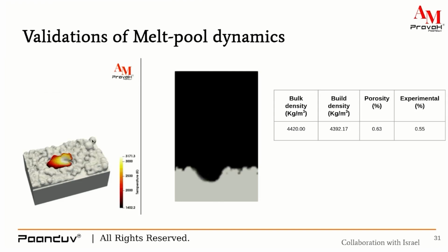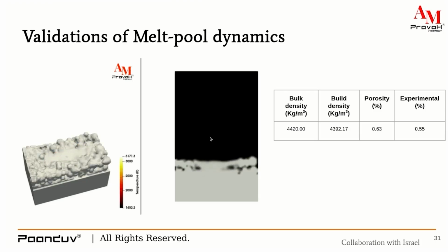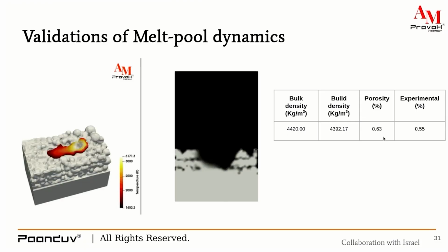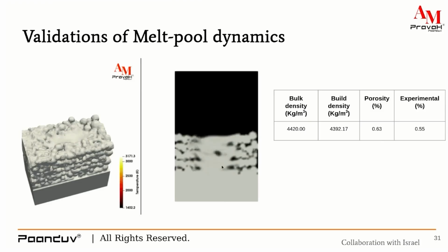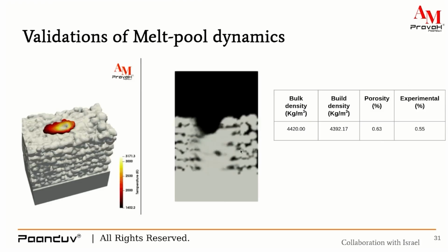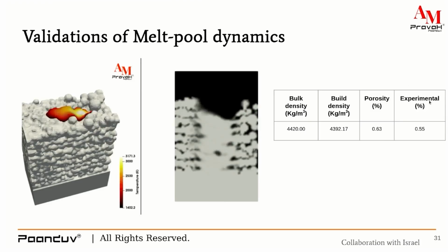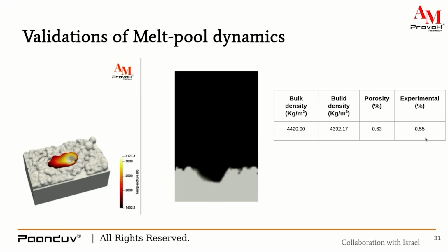Right there, you can see the temperature evolution and Q, which is the heat input in watt. You can quantify that, and you can see how we have achieved the width and the height of this particular bead. This is compared with experimental results and are in good agreement with the experimental data. These are the snippets at different time steps, different times of this particular animation.